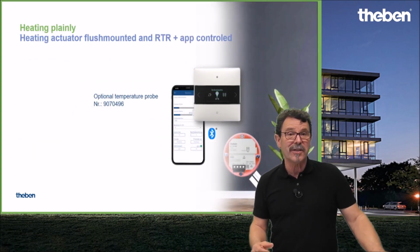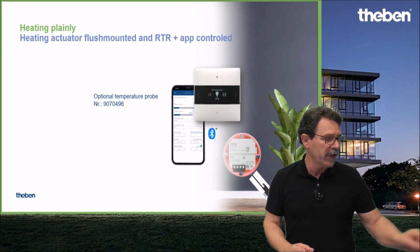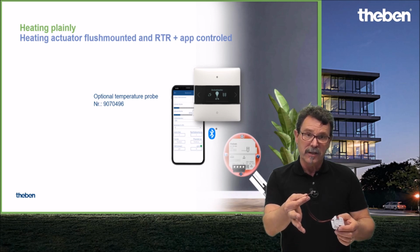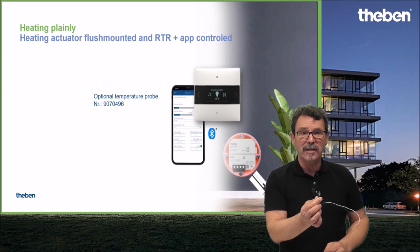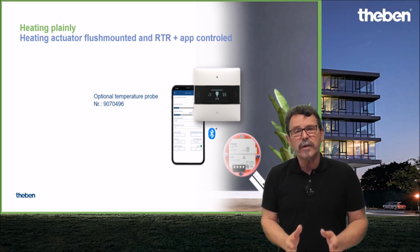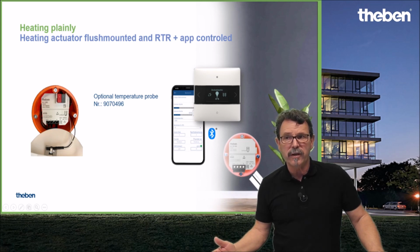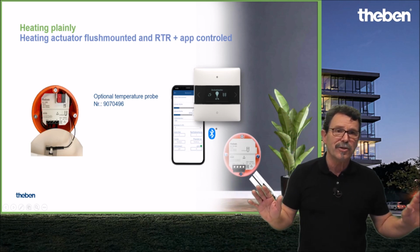Yeah, or you can do some small, fancy, hidden heating control with our flush mounted actuators. We have here, for instance, these flush mounted actuators, super flat, fitting ideally in such flush boxes. We have binary inputs here, and the input E2 you can link with such a temperature probe. Tiny, fancy, little, small, you discover here, and you link it directly to this actuator, and you have a discreet, nicely invisible temperature control, for instance, in your living room. So that means you put it in a flush box, you put a cover on the rear side, you stick this temperature probe on, the temperature probe is linked to the binary input, and the temperature controller is ready to go.